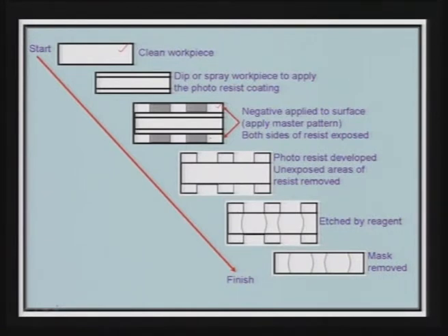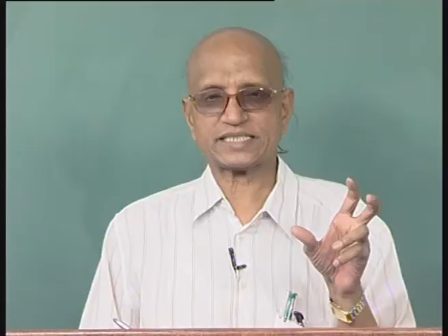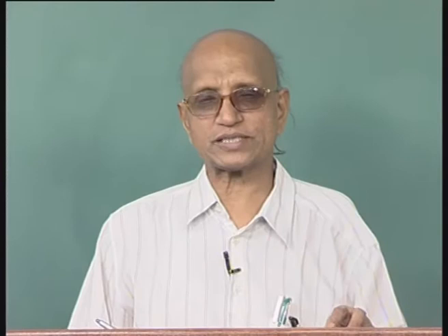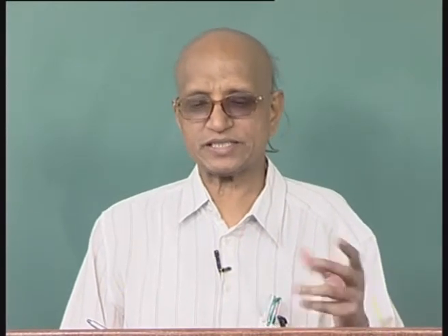I will explain the whole of this process later on also, but just to give the idea that in chemical machining, instead of machining from one side, you can machine from both the sides, so that the machining rate will increase and total time taken will be reduced.